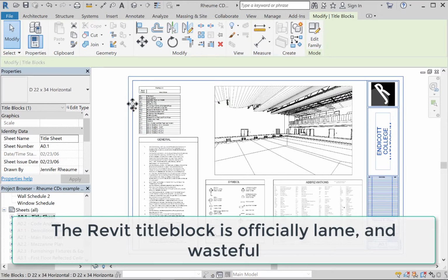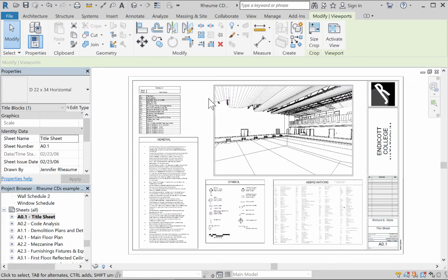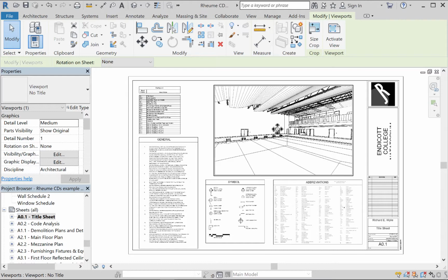Note that on the left side of the sheet, we usually leave an inch for binding, physical binding. And we're going to create a bunch of sheets, including the title sheet. We're not going to get everything on there just yet, but you'll see that there is typically on the title sheet a perspective view, a drawing list, general notes, an indicator of symbols, and usually a list of abbreviations, although we use a lot fewer abbreviations, so I'm going to recommend that you only list the ones that you're going to use or that are industry standard.